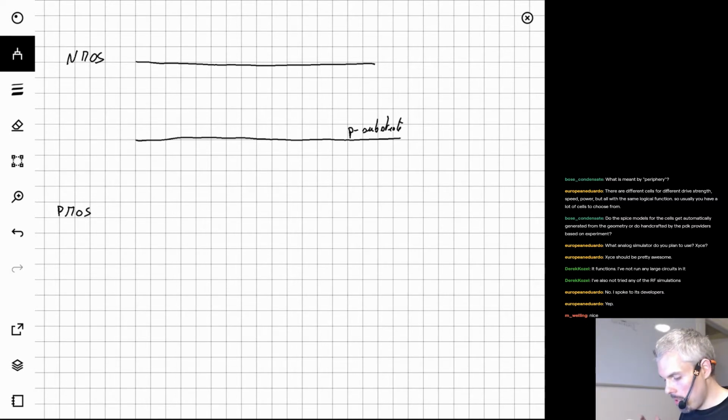In this particular process, we start with a P-type wafer. The first thing you're going to do is create the gate. You're going to have a very thin layer of oxide created here, which is called the gate oxide, which is really thin. And then above that, you will find the actual gate, which is made of polysilicon.